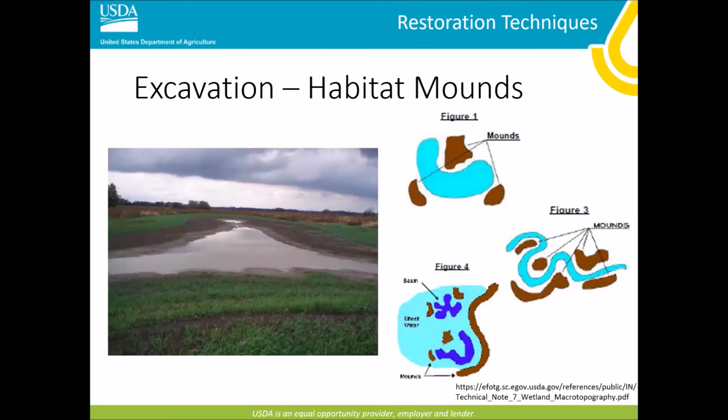Their placement should not create flooding. They really should not be embankments. These are not structural measures. You can see from figure 4 right there that we are holding back a little water from the placement of that macro. But this is not a structural macro. This water will be going around this macro. It'll be on both sides of it, more than likely around that embankment. So keep that in mind when you are getting rid of this spoil, to not try to impound too much water.